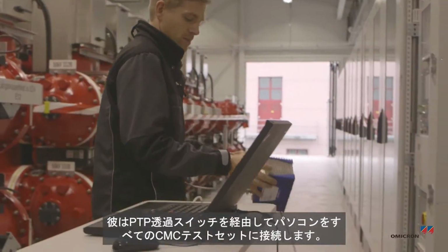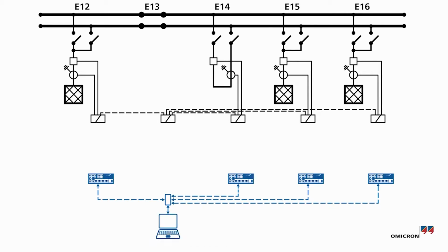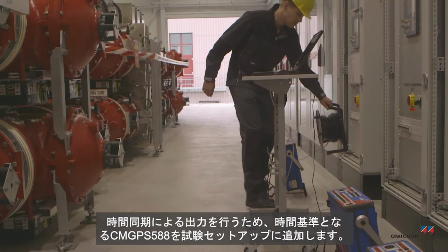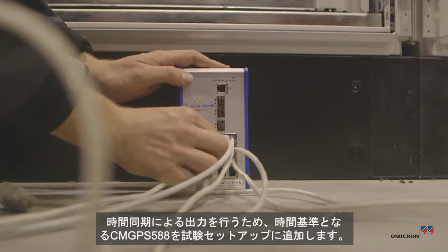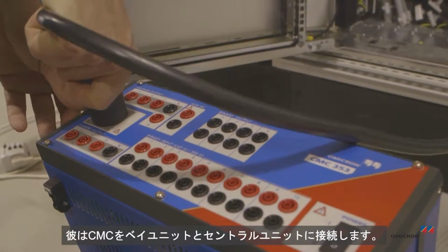He connects his laptop to all of the CMC test sets with a PTP transparent switch. For synchronized injection, Florian adds a CM GPS 588 time reference to the test setup. He connects the CMCs to the bay units and the central unit.